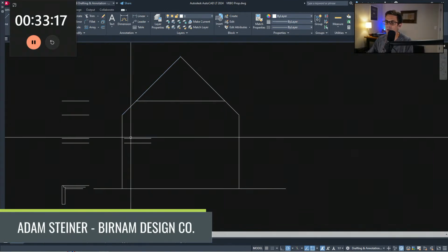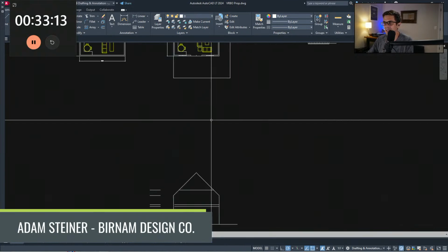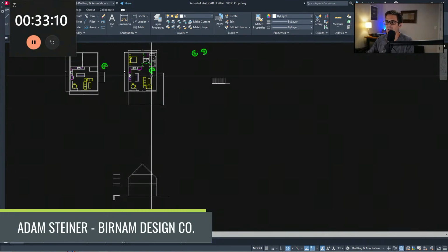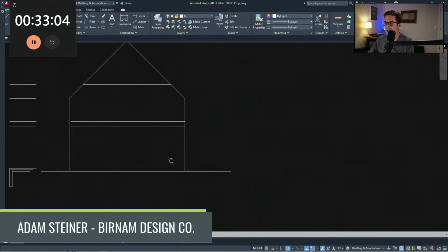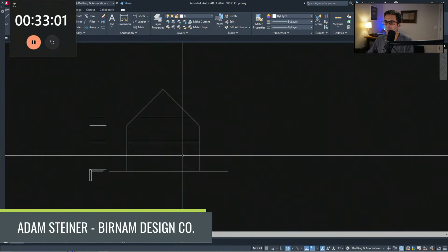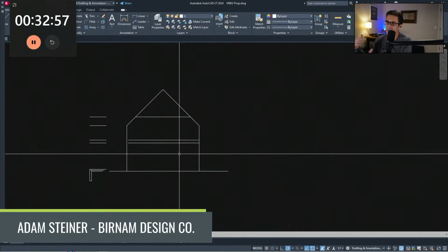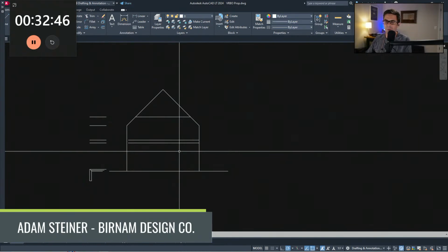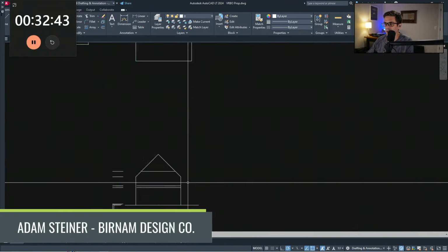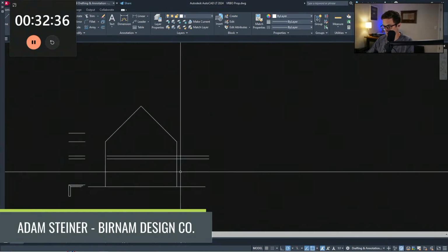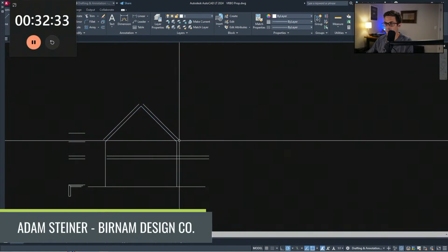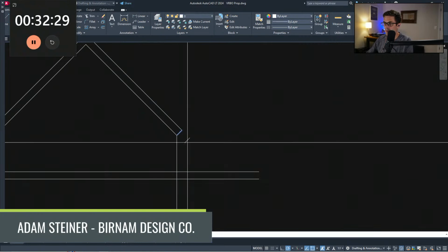You won't have full head height in the corner of those rooms, but that's okay because you don't need it there either. With a 12-12 pitch, you should be pretty close to full height. Yeah, you are. When you get to the top of the stairs, you're pretty close to full head height there. And so yeah, that's probably what I propose. It's a little bit cheaper to do that knee wall than a full stud wall. You're paying less in siding, less in lumber, less in drywall. Although drywall you might not get a credit back for because they have to drywall those slanted ceilings and all that. But I think that's the route I want to go with it. And then we could do a cool flat porch roof on it. Something like this.